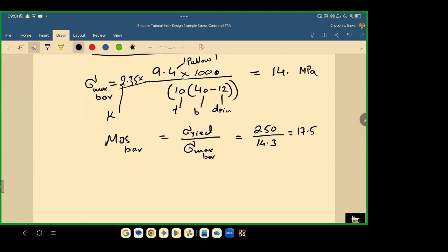So let's now, because a lot of the time I just do a basic sense check to understand if there's a calculation mistake or not. Because a basic sense check will tell me that with a factor of safety of 1.5, I was getting a load of 19.8, I'm only halving that load approximately, right? So my margin of safety cannot go 17.5 times.